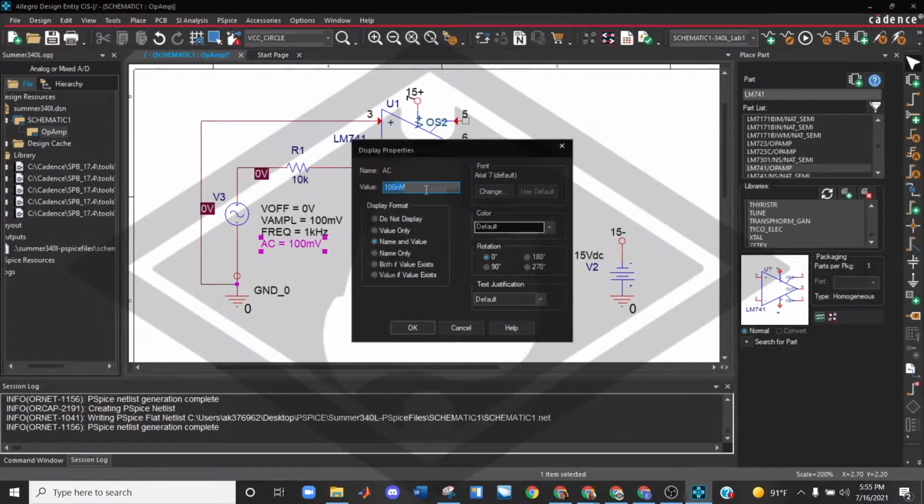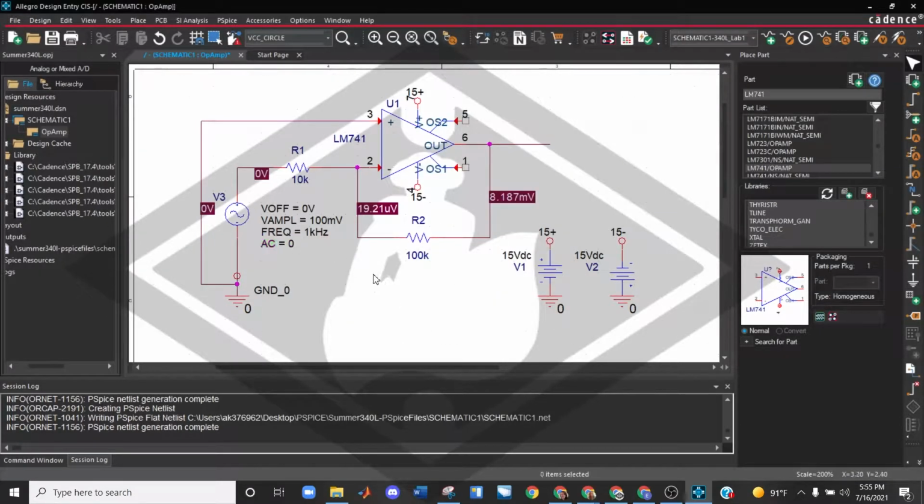So I'm going to actually leave this empty for now. Oh, I can't. So I'm going to put 0. And I'm going to do just a plain transient response. So for these values, these were the values of the op amp that I had for the physical breadboard circuit. And this is the inverting op amp that I made.